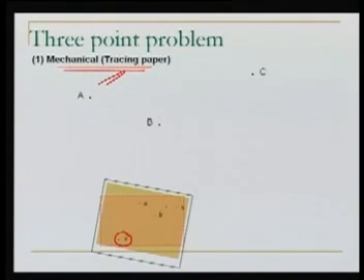And what we do, from this small p, without any concern for these points at the moment, we draw rays to A, to B, and to C. This is very important. What are we trying to realize here? We now have 3 rays to A, B, and C. So somehow I have found the alpha and beta angles between these rays. Now one thing is very important here.